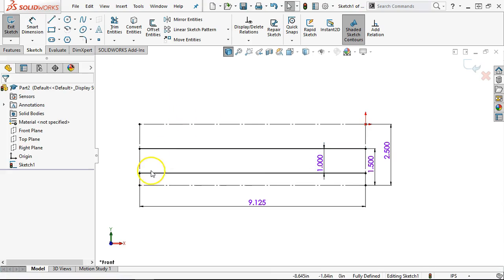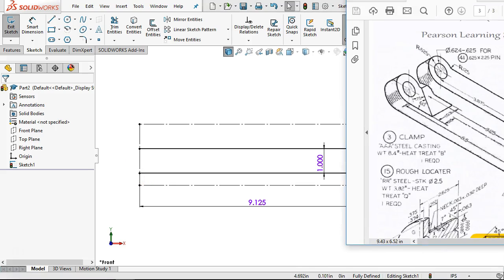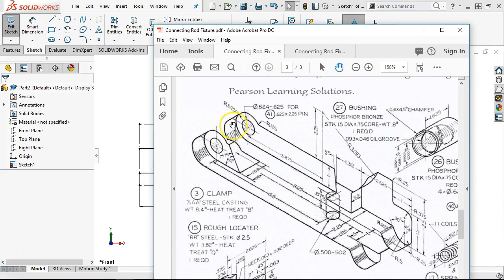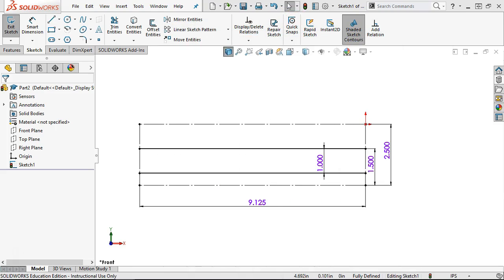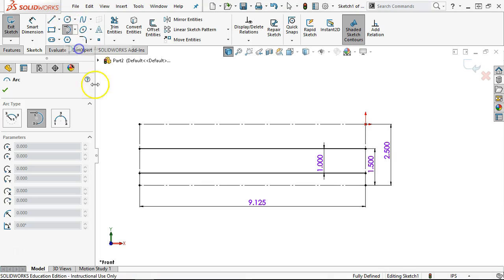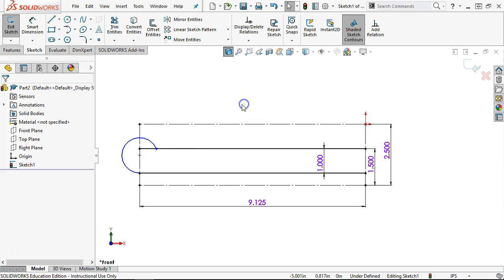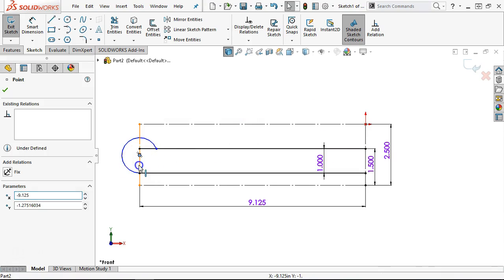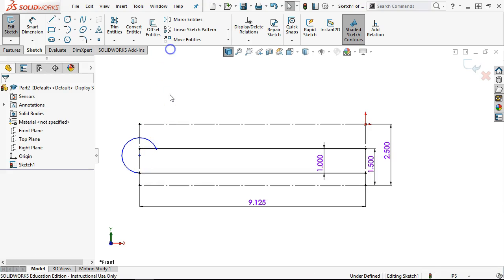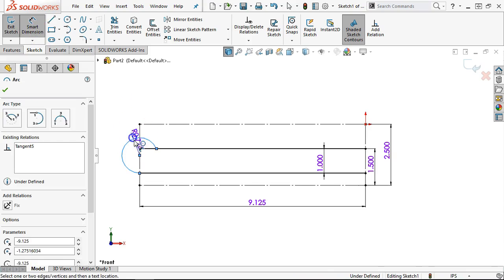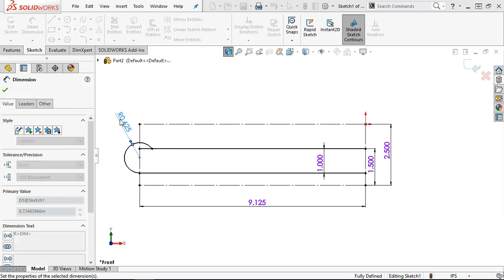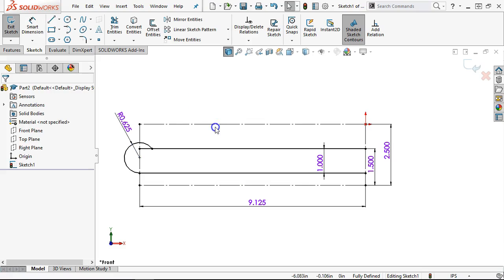Then that end geometry is going to come off tangent, but then up and over. So let's go ahead and resolve that one as a tangent arc. I'll just bring it back to locate, and we'll make sure that goes coincident. We have a radius of 0.625, and so that gives me a location.